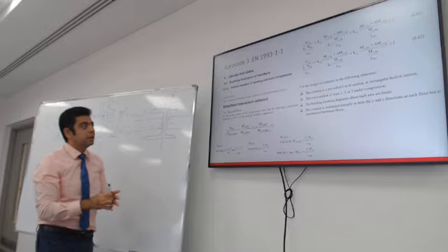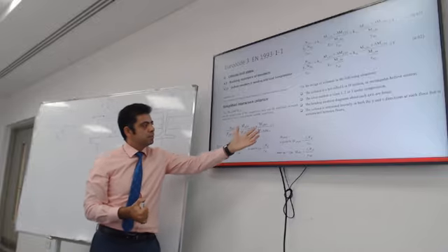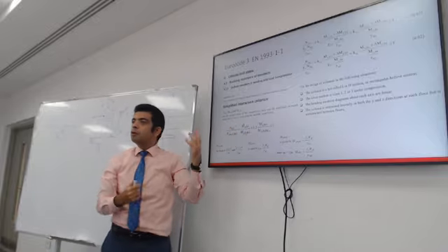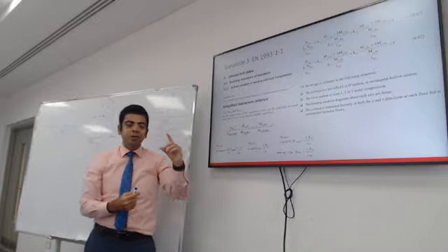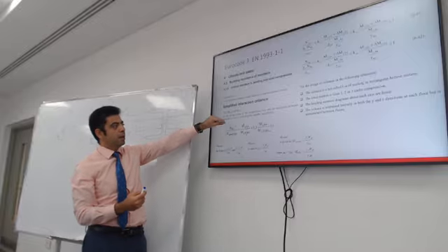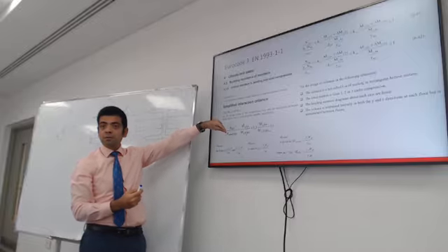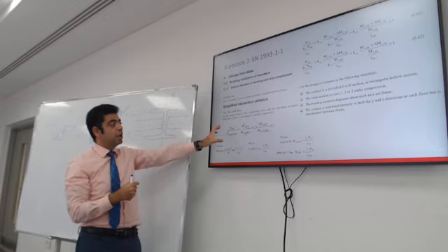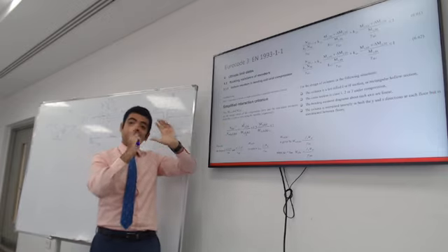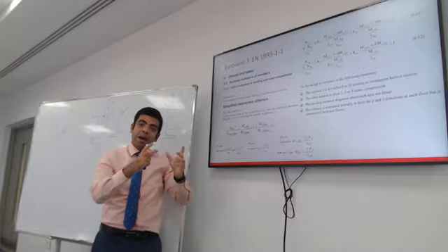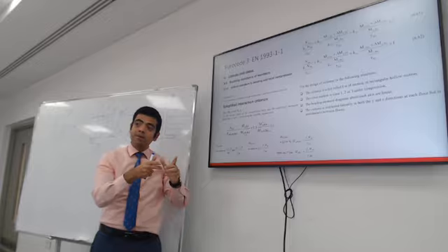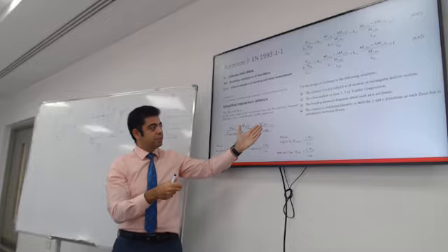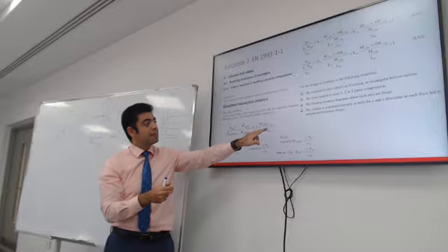And that's why you introduce this, some codes call it like a unity equation. You make sure that the ratio between the actual normal force compared to the capacity, the axial capacity of the column, you add to it the actual moment divided by the capacity of the section in moment about y and about z, is less than 1.